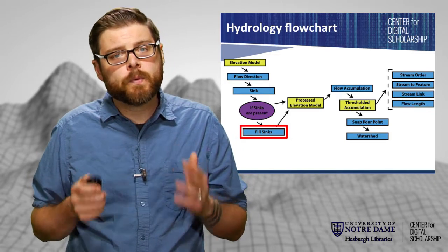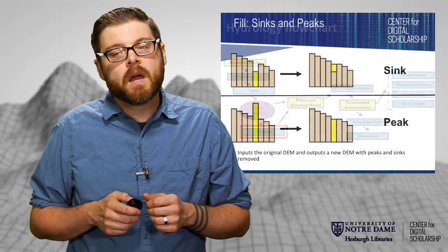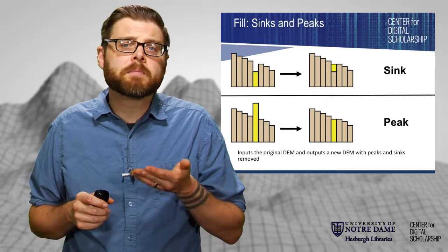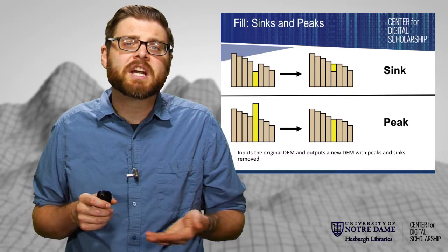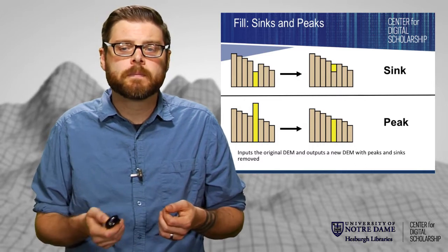If there are any sinks, we want to fill them in. And basically what this is going to do is raise them up to the minimum value. So it's not going to change how water would flow through that area. It's just going to make it so it doesn't collect anymore in that particular spot.